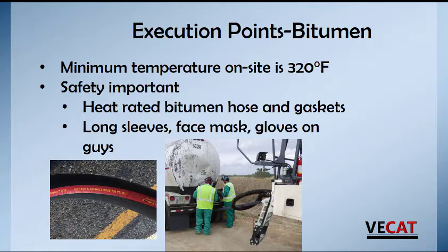As you can see here, the operators or the people connecting the truck to the machine have to have face mask shields, proper PPE for dealing with this. We also have to have hot rated hoses, gaskets, and connections. So it's very important to remember all this well ahead of the process.